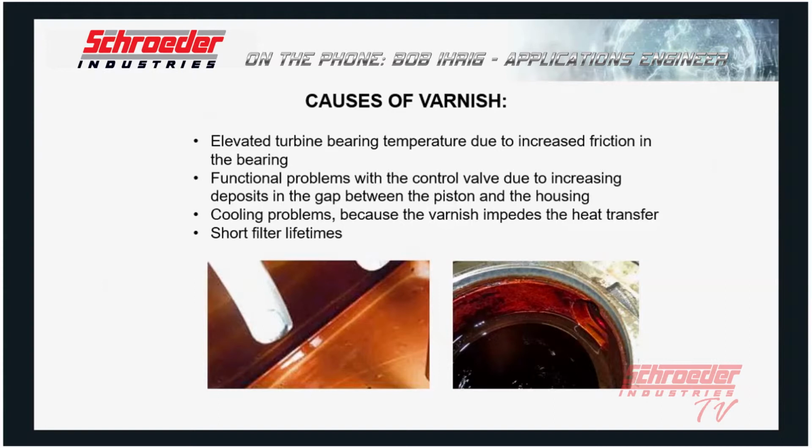Other than that, thermal stress due to friction or perhaps microdieseling, that's also a big source of varnish creation, as well as electrostatic discharge. We'll talk about what that is and how that's related to oil aging, as well as hydrolysis, the reaction with water. And there are other chemical reactions that can cause premature oil aging and the associated degradation byproducts. Those other chemical reactions include mixing unlike oil, as well as topping off or adding either inappropriate or too much of additive concentrations, and so on.